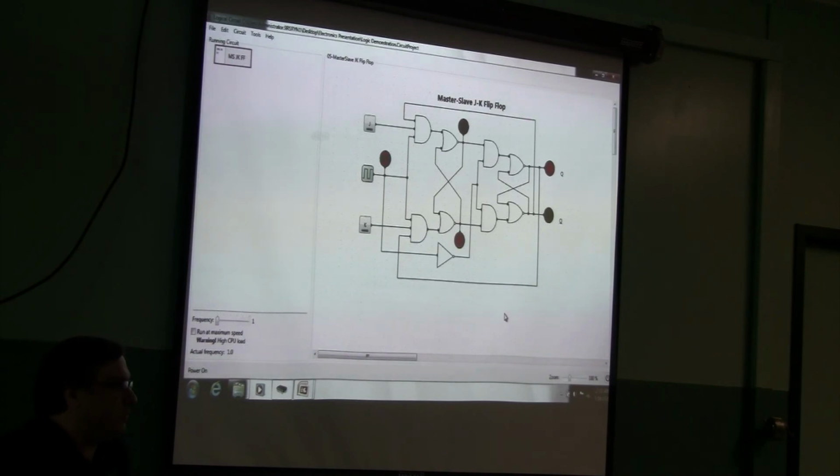So if you're using 3.3 volts, would these 7400 chips still work? No, 7400 chips are very specifically 5 volts plus or minus a quarter volt. That's the rating on 7400 series logic chips. They are definitely 5 volt chips.